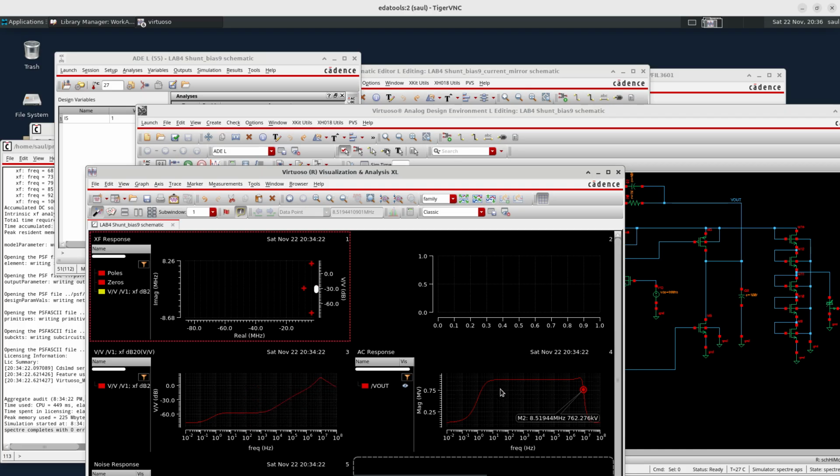Okay, so we have this. Typically this curve is extremely low at very low frequencies, and then starts deteriorating at very high frequencies, because there's basically no gain anymore that can filter the variations, and it may even get positive at extremely high frequencies. But at extremely high frequencies the power supply is normally filtered.